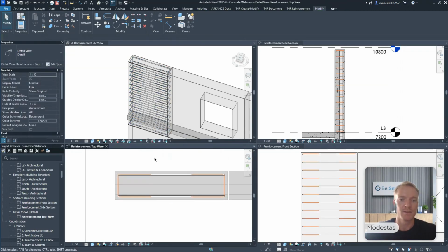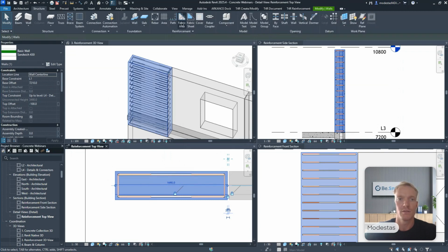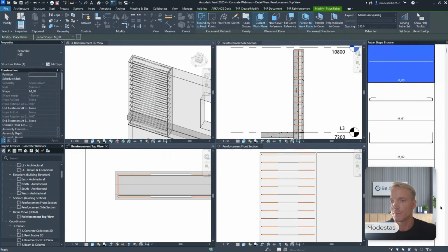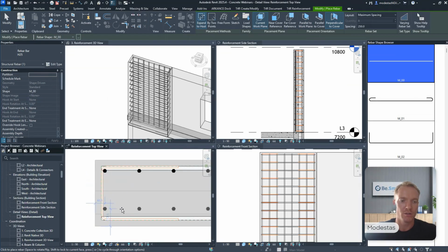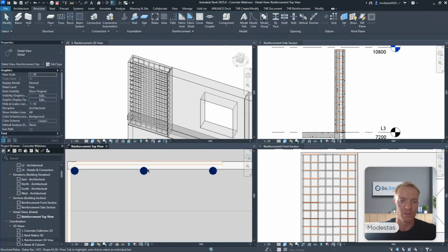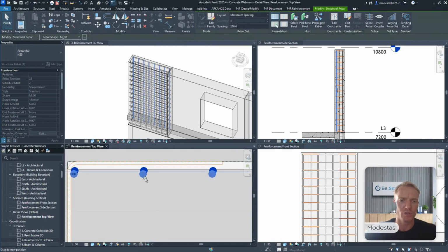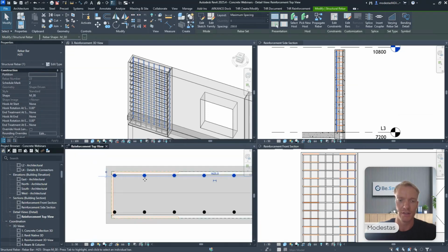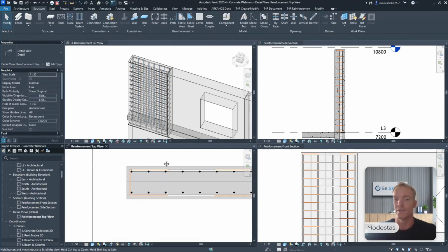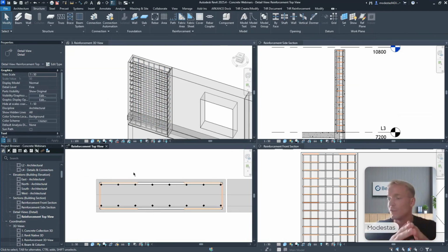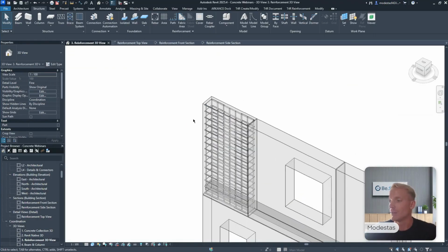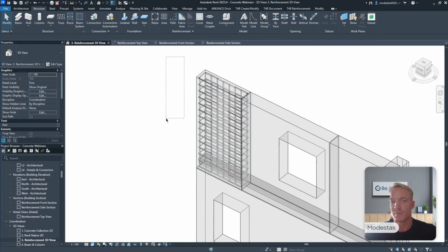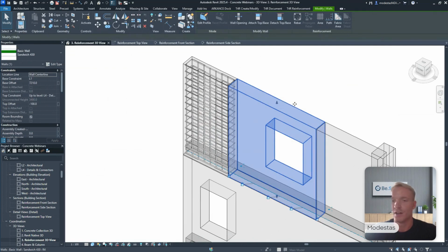And let's place vertical rebars. And I'm going to change the placement orientation to perpendicular to cover. One here, and maybe one here. And as you can see, I already made a mistake. I'll need to adjust the positions manually, and that can lead to additional effort to get the correct result that you want to have, right? And the other thing, it took me quite a while to get the reinforcement placed. How about the other panels that are around it, right?